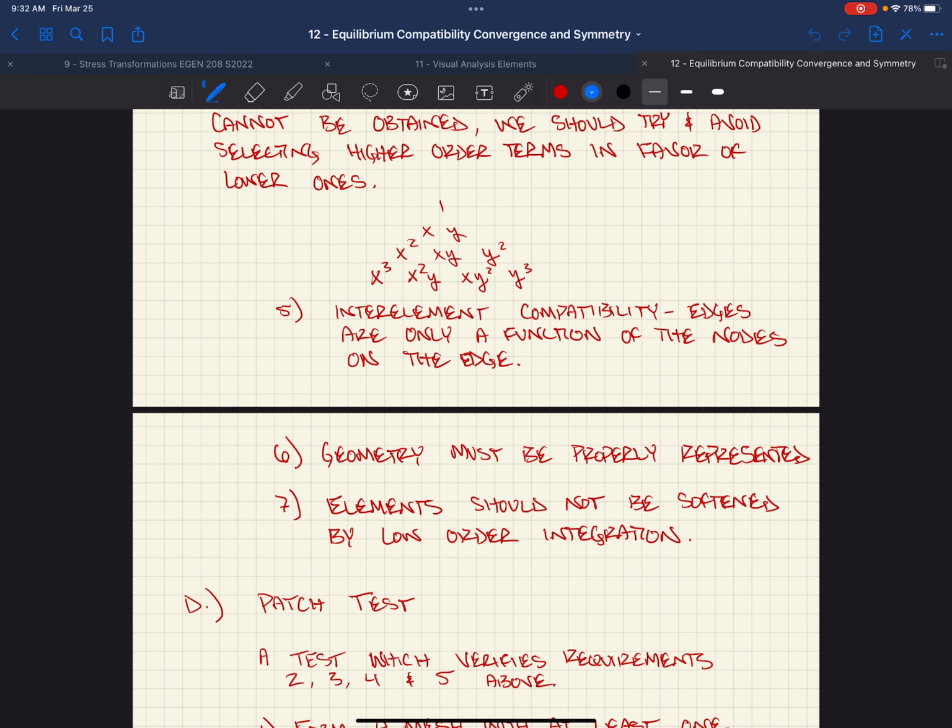How does, you're saying that we use a cubic shape function instead of what should be a quadratic function for the displacement along the beam element? Yep. And that adds stiffness? How does that add stiffness? Because you're losing a contributing term, right? Your displacement function should really have a term in it to the fourth power that's contributing to the displacement at any given point along the beam.